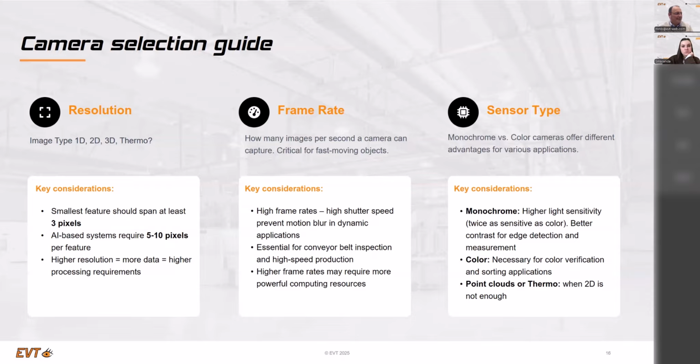If you trust in the subpixel accuracy, you could use a lower pixel resolution. We have proof that it works, but it's your decision what fits best for your needs or what you trust. In the end, it's a question of proofing and trusting. So you can test both with the EyeVision software.